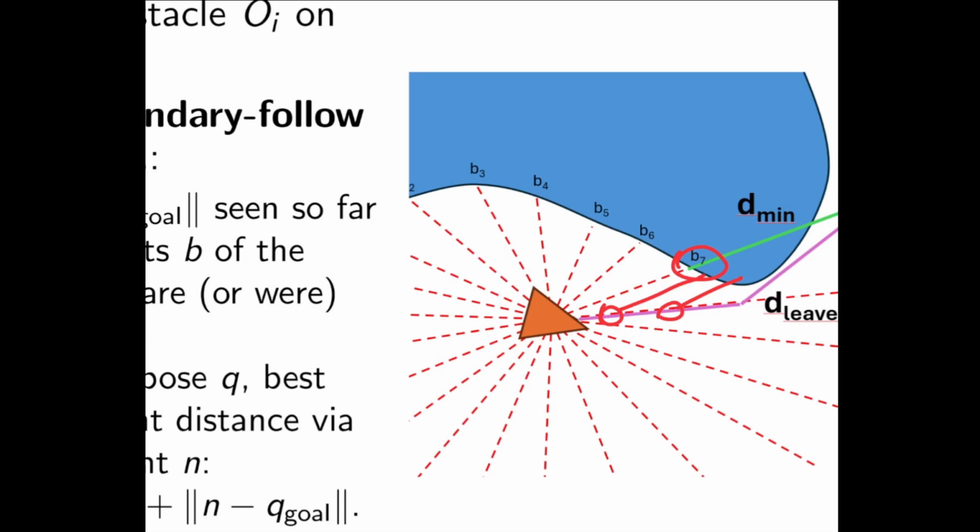they have, for instance, the simplest to understand is the sonar one. They just emit a sound and wait a few milliseconds to receive the answer. If they do not receive anything, it means that there is nothing in this path, and therefore that this is free. Of course, it may be that it's something that absorbs the energy and you don't see it, but then you will crash into it because you will not detect it. If they do not answer, then they normally return the maximum range. If, for instance, the maximum range of this sensor is 10 meters, then they will tell you 10 meters. Then up to 10 meters, there is nothing. After 10 meters, I don't know.